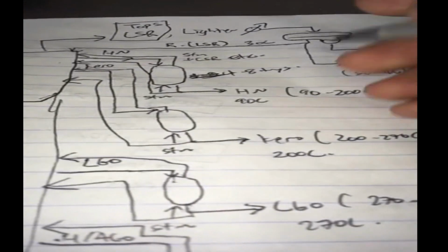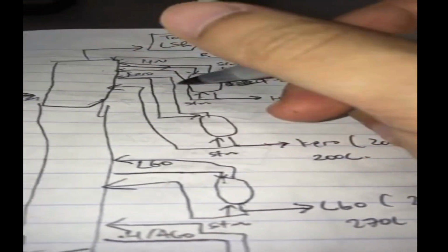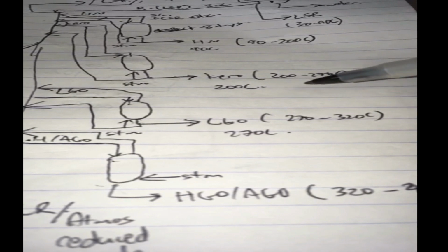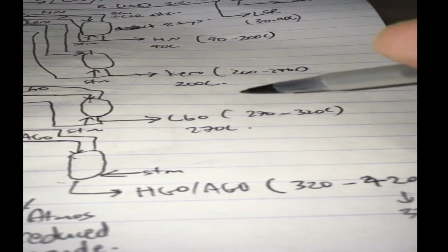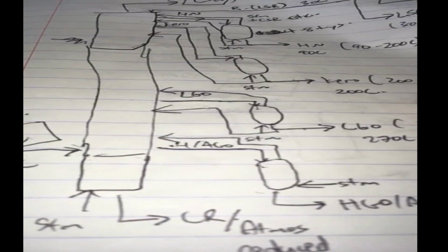120 degrees. I can use more heavy naphtha to heat it up, or I can use the kerosene. So I can pump my crude here, cool the kerosene down a bit, send it back. And then crude oil will reach about 200, maybe 180, 170. If I heat it some more, I can use this light gas oil fraction, use the crude oil to cool it down, and my crude oil will heat up in a heat exchanger, send it back into the tower, and now there you go.